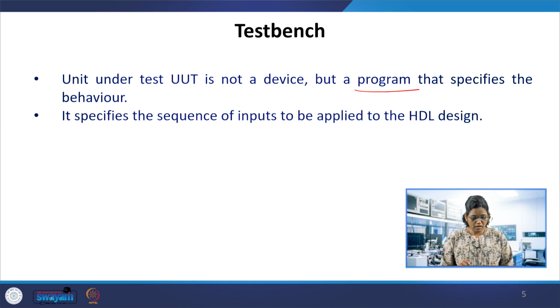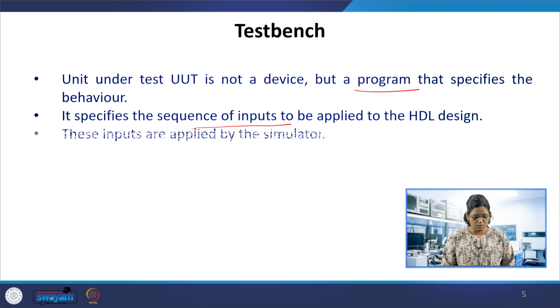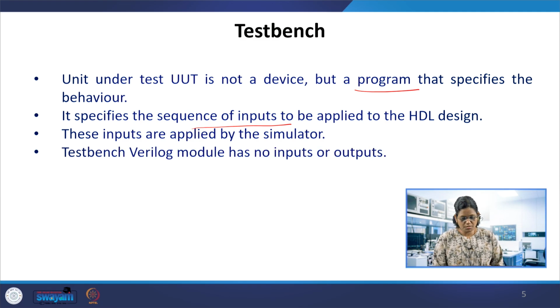So, it specifies the sequence of inputs that is to be applied to the HDL design, that is the Verilog module. Also, it observes the outputs. The inputs we specify for the module are applied by the simulator to the module. It's very important that the test bench module, like any other top module, doesn't have any inputs and outputs. The module will have only the module name, and there are no inputs and outputs. So they are specified in the test bench.